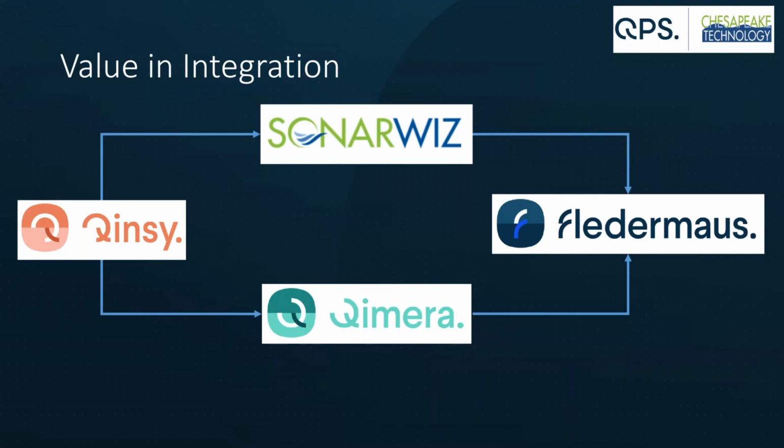Okay, I see here, Marcus, there are a couple of QPS related technical questions. Do you want to take those? Yeah, we'll go ahead and grab that. The first one I see is, how long did it take to roughly process the bathymetry? Between import, applying the tide files, processing, and then actually doing the cleaning, I did most of the cleaning using some of our 3D filters and spline filters. Then I only had to do some spot cleaning here and there where there was some extra noise in the data, whether it was from air in the water column or whatever the case may be. Overall, it's about 30 to 45 minutes total. So that's a great question.